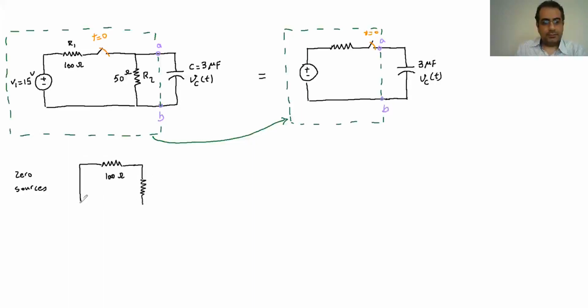we have this resistance here, which is going to be 50 Ω, and then we have these A and B. If you look at it from this point and calculate the RT, the Thevenin resistance is equal to R equivalent for this system.